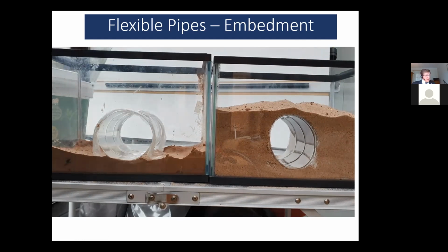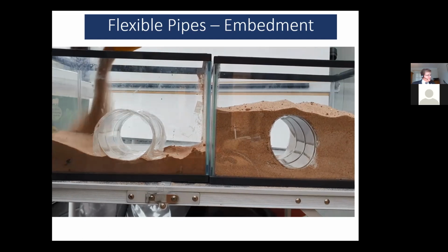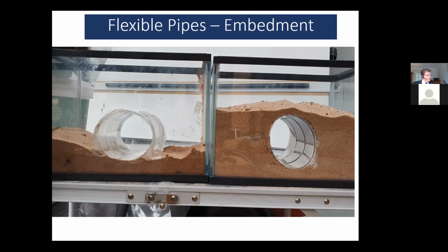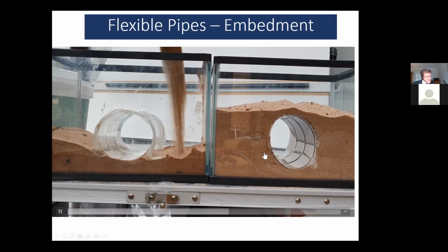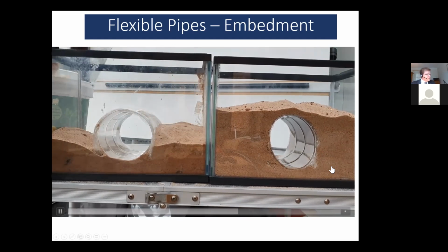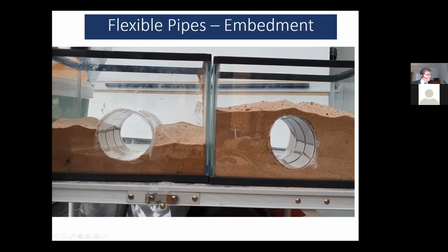Now sands vary quite a lot, as we'll show. This is quite a good material for compaction. This does flow quite well, and it's flowing underneath the pipe quite well, but compacting this bit underneath can be really tricky with some of these materials, and there's special tools developed and all kinds that get used in nations, but I don't see used in the UK.